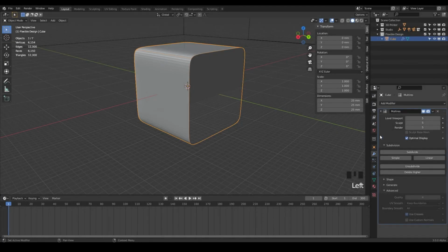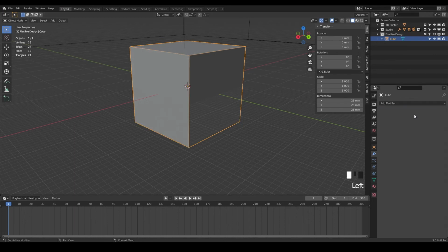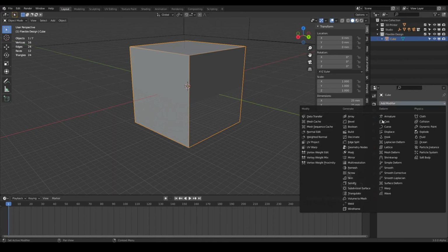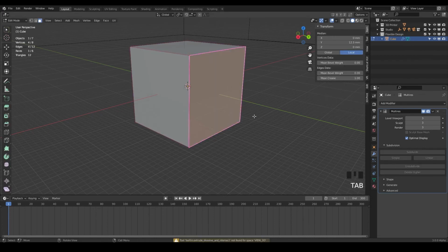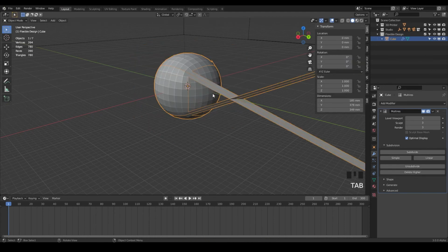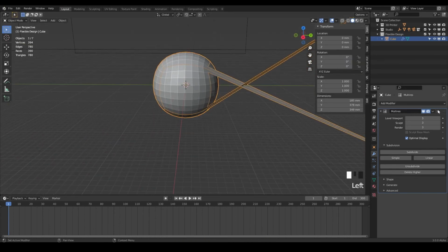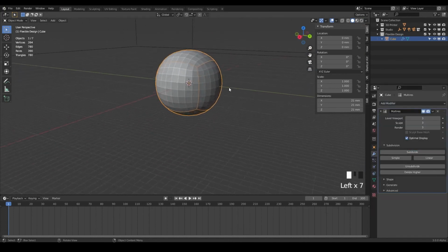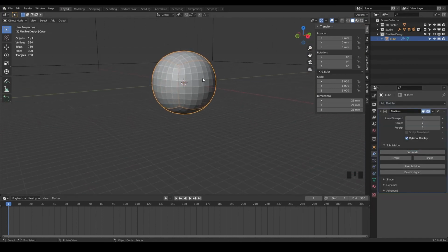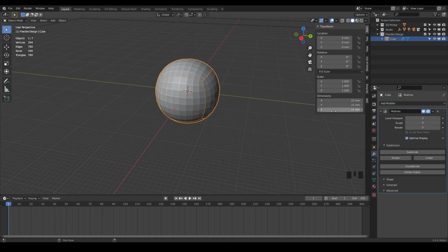We haven't gone over the subdivision surface modifier, but let me go ahead and delete this one here. And say we use multi-res and subdivide a few times. And I'll uncrease this. We'll just select all and drop the crease to 0. I've messed up the math, so let's just redo that. Multi-res, subdivide 3 times. There we go. So now you've got just a nice little ball there. And that is with the multi-res.